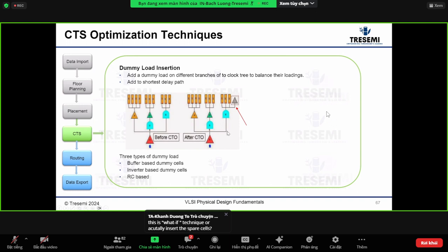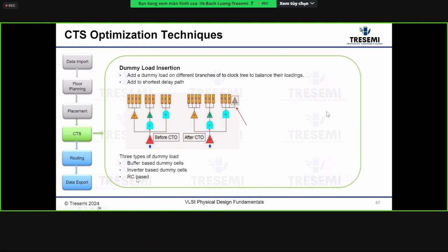We just add wires to the flops that have hold time issues, instead of adding buffers or anything. It will slow it down. If it's barely missing, let's say, a couple of picoseconds, we figure the wire this wide and this many microns long should be enough slowdown for those 2 picoseconds. So understanding this will help you quite a bit later on in your job. Good point, Dan. Thank you.